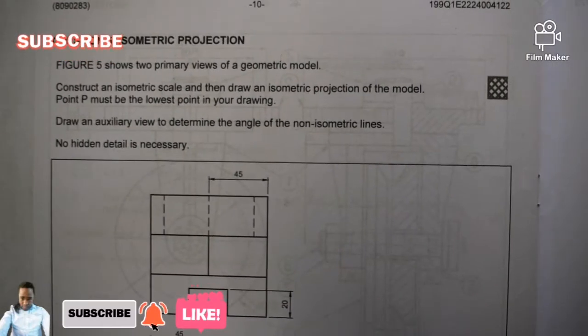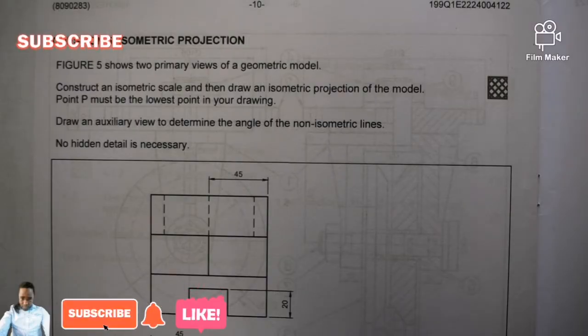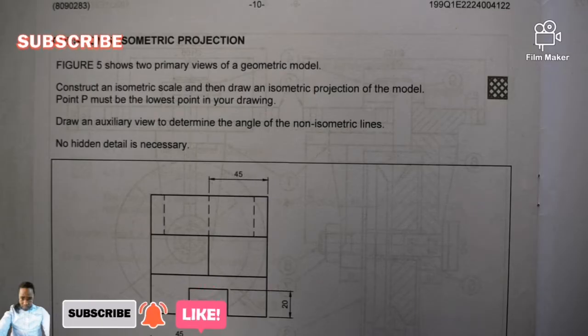Figure 5 shows two views of a geometric model. Construct a suitable isometric scale and draw an isometric projection of this model. Point P must be the lowest point in your drawing. Draw an auxiliary view to determine the angle of the non-isometric line.